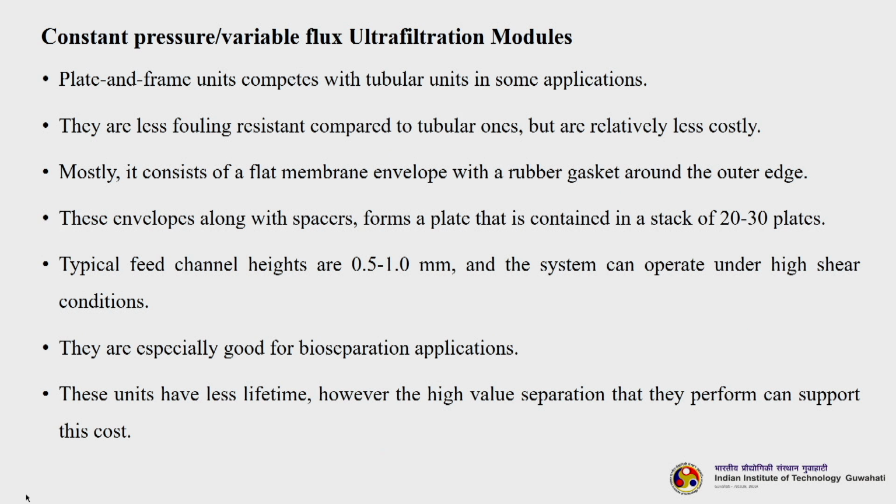The next is plate and frame units. They compete with tubular units in some applications. They are less fouling resistant compared to tubular ones, but are relatively less costly. So, as I was telling you, if you are going for an application which is not a therapeutic product application, you can always go for a plate and frame system or some other membrane applications. Mostly it consists of a flat membrane envelope with a rubber gasket around its outer edge. These envelopes along with spacers form a plate that is contained in a stack of 20 to 30 plates.